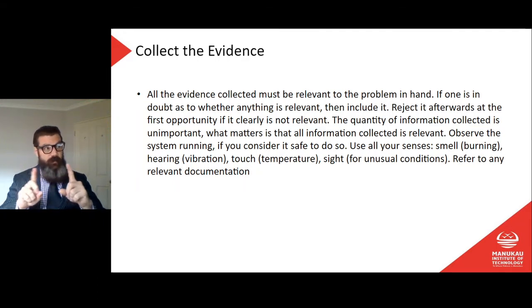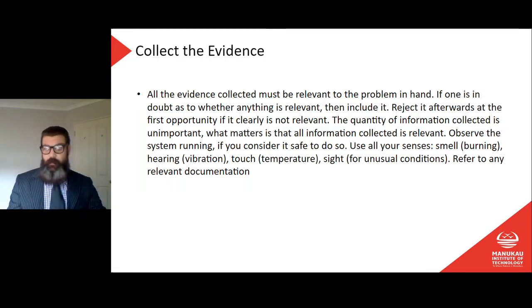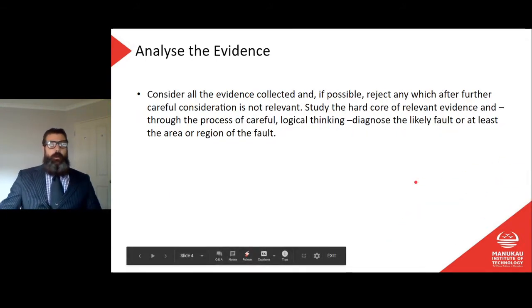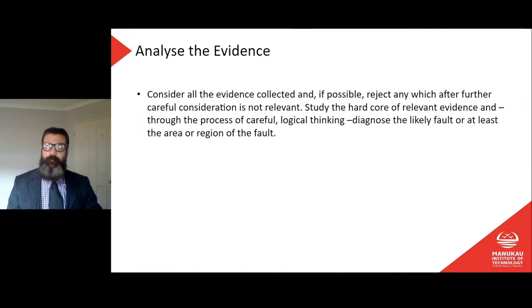But again, the card reader screen and the pumps are totally separate things. They'd be on separate circuit breakers. The fault in one can't affect the other. They seem totally unrelated. But if I dig a little bit deeper, I find that the emergency stop switch can turn both of them off. So there's my common point. That's where I should be looking. So if we have 2 faults that seem unrelated, look for the common point. Or if we have 2 faults that are related, look for that common point. What relates them together? What brings these 2 things together?